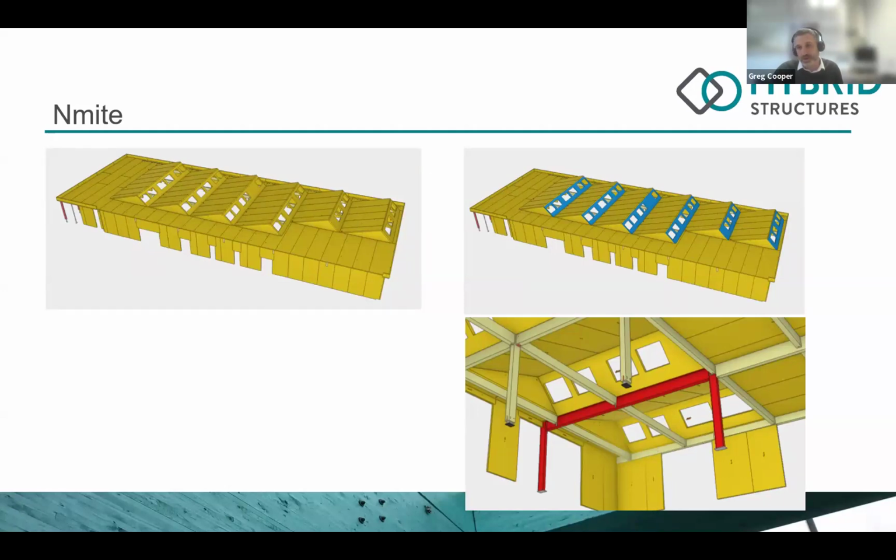And we spent a long time trying our utmost to get this to work in timber, but the physical size of the beam needed to be in timber would have detracted from the space that the architect and the client wanted. So we had to mix the materials in small areas like this, where we use structural steelwork to ensure that the deflections were limited and the door could work throughout the life of the structure. As you see there, it's just a single beam, goalpost frame, tied into structure to make the structure work.